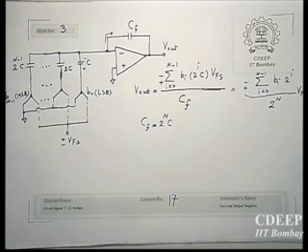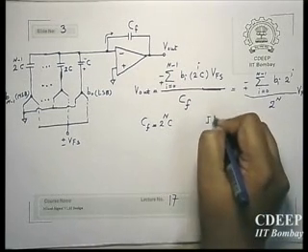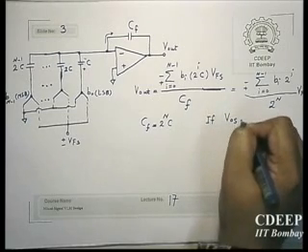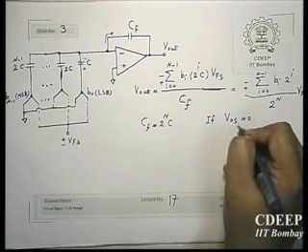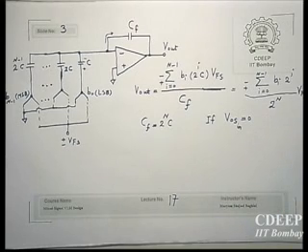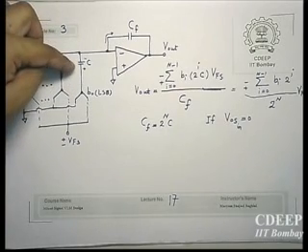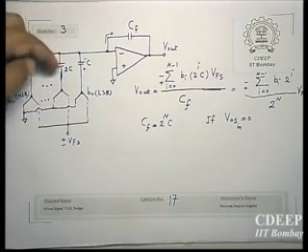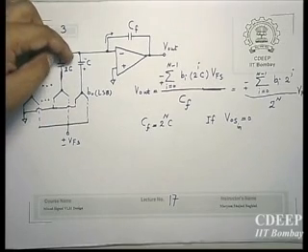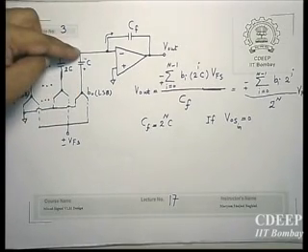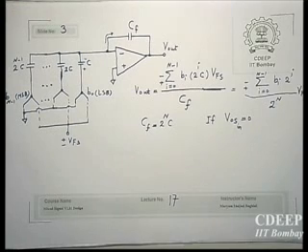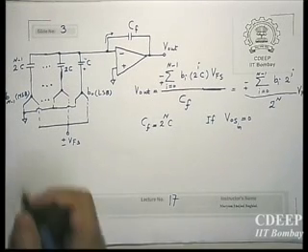Okay, so this is if the input offset voltage of the op-amp is equal to 0. But if the input offset voltage is not 0, eventually everywhere this charge Q won't be simply C into V full scale or 2C into V full scale. Eventually it will be C into V full scale minus V offset. Therefore, everywhere you will have a new relation.